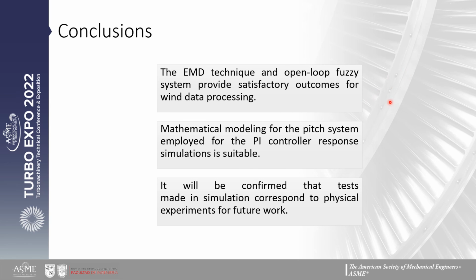We have 3 different conclusions. The first one is that the EMD technique and the open loop fuzzy system provide satisfactory outcomes for wind data processing. The next one is that the mathematical modeling for the pitch system employed for the PI controller response simulation is suitable. And the last one is that we need to confirm that the tests made in simulations correspond to physical experiments, for future work.